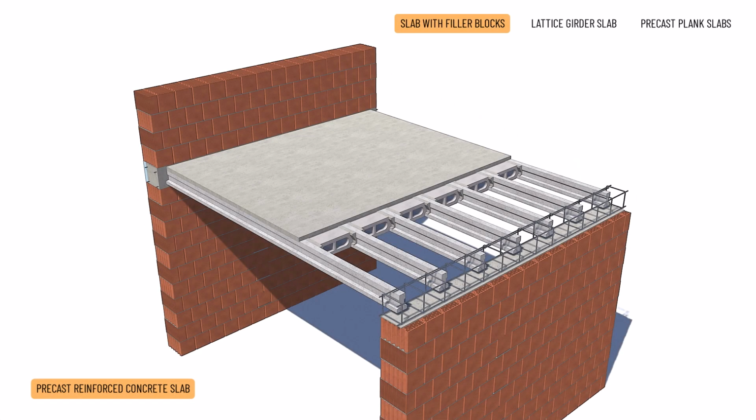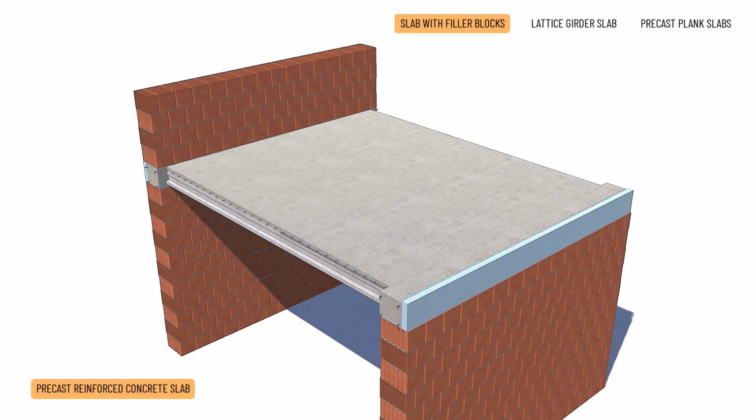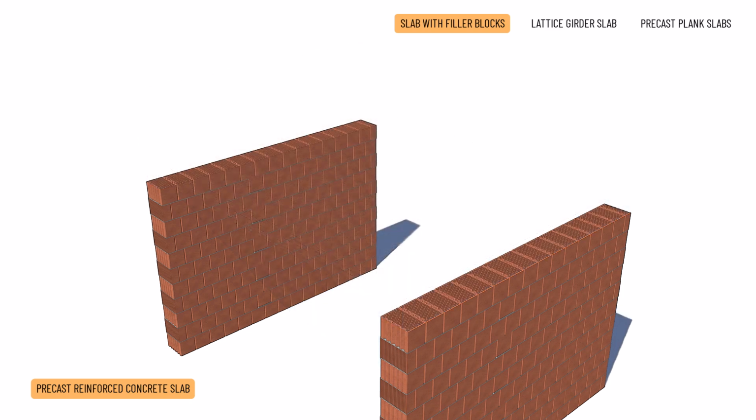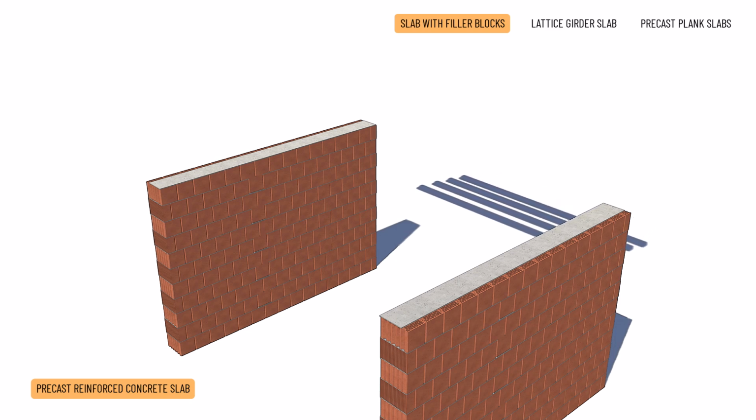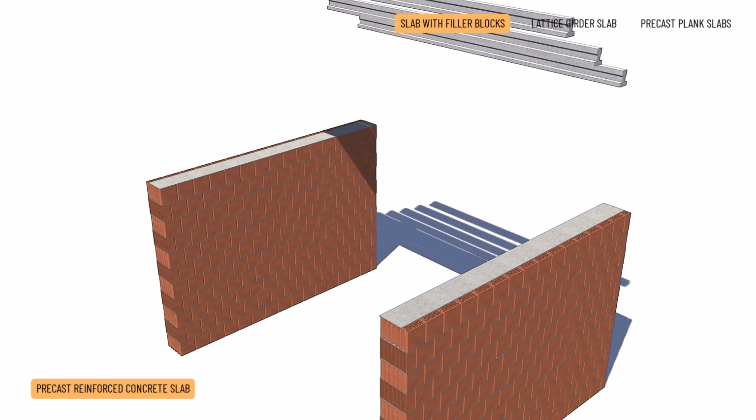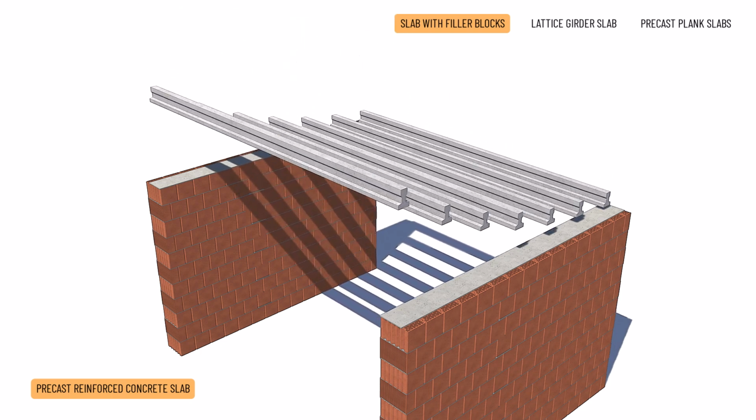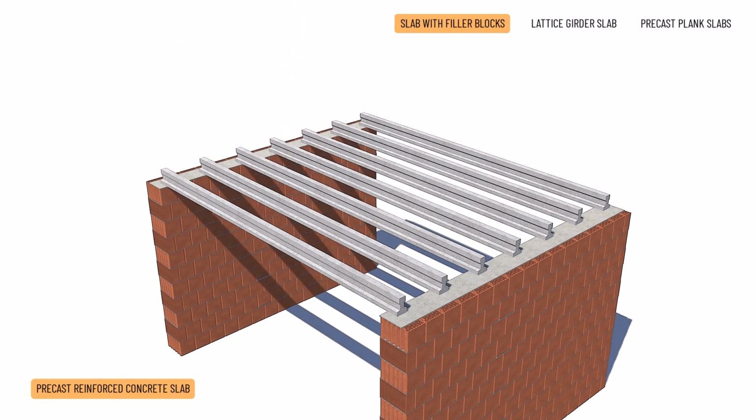Precast reinforced concrete slab with filler blocks. In our example, we show a classic E-type beam slab with a wall spacing of 240 to 660 centimeters. The primary load-bearing structure for precast reinforced concrete slabs with filler blocks are precast reinforced concrete joists placed with a 60 centimeter axial spacing to bridge the span of the floor in one direction.